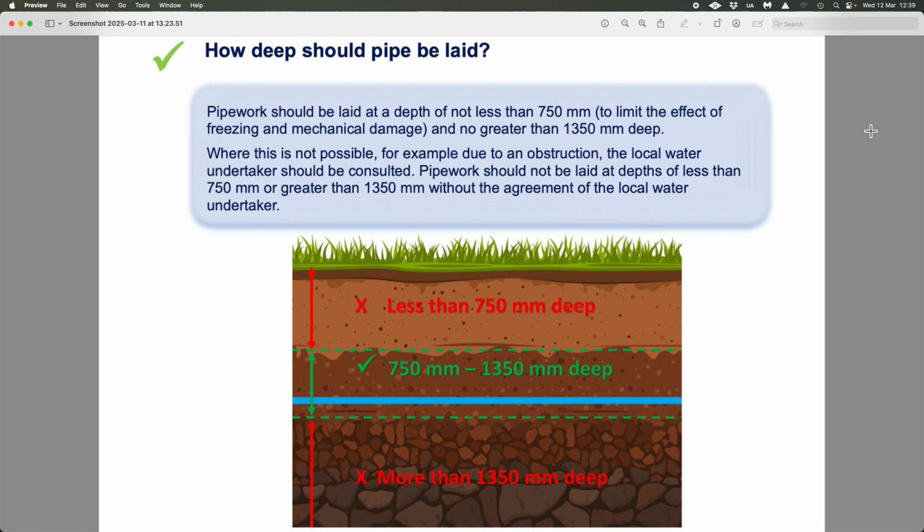Now that reduces your delta T of how much you actually need to heat that water up. So you could actually say, instead of 10 degrees, you've got 15 degrees stored water. You don't need to heat up to 35 to get 45 out. You can actually just heat up 30 degrees. So you can change your delta T, and we'll have a look at those in a second and see what difference it actually makes. But again, it's all about squeezing the most amount of efficiency that you can out of a hot water system and getting it right.